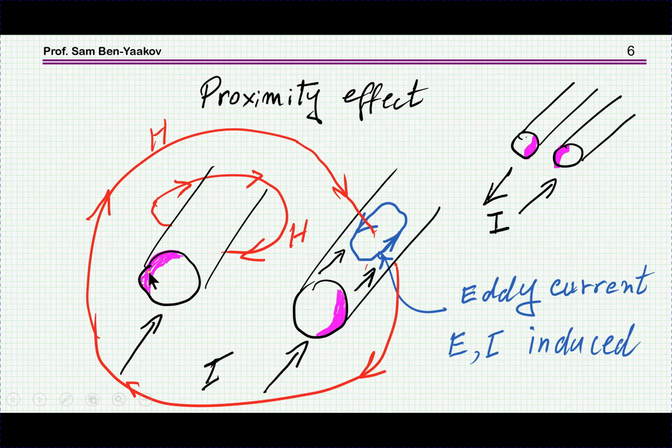So we are going to have a situation in which only part of the diameter of the wire is actually being used, so the equivalent resistance, the so-called RAC, is much larger. Of course, if the diameter of the wire is smaller and smaller, then most of the current will be passing throughout the cross-section. And if the currents are in the opposite direction, we're going to see this crowding adjacent one to the other. So this is the eddy current.